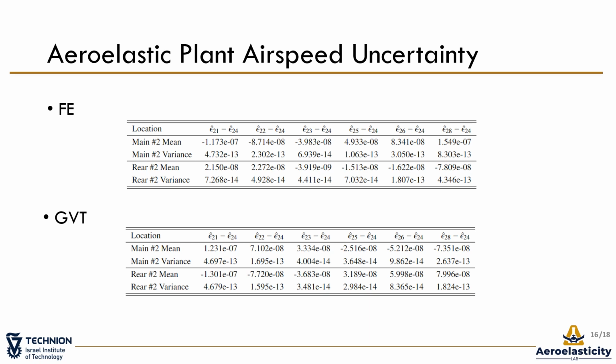The tables show the errors in prediction of the strains at the unmeasured locations. These errors are small, in the order of 0.1 microstrains, indicating that an aeroelastic model with 12.5% offset from the flight speed yields good prediction.